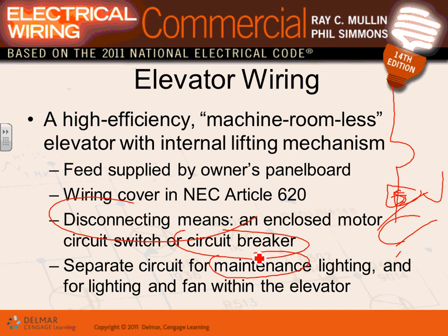So be aware, if you have an elevator, you have to have the following. Number one, a circuit to feed the elevator. Number two, a circuit for the light and the receptacles in the elevator room or the machine room. Number three, a circuit to feed the fan inside the elevator car itself, and another circuit, guys, for the light inside the elevator. Does that make sense? So all these come typically from a panel. What they do, guys, for elevators, they have a feeder and an elevator panel, and they feed the light, the receptacle, everything for that elevator from that little panel. That's what they do with elevators.